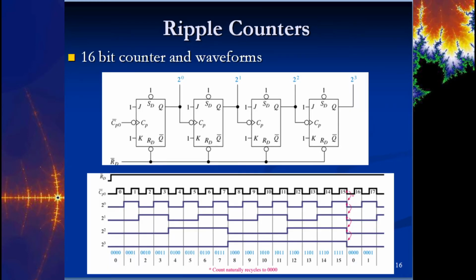Right? This is a 4-bit, and the only difference between this one and the other one is you just double the amount of counts. So a 3-bit, you can see it, it's working itself. It hasn't changed. If you ignore this very last flip-flop, Q0, Q1, and Q2 essentially just repeat over and over as a mod 8 counter. It's just that now you've added another output, and so you've doubled your count. Okay? So in this case, we're counting from 0 all the way up to 15, and then 0 through 15.